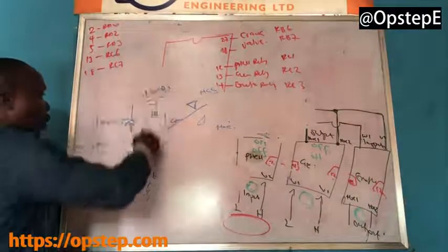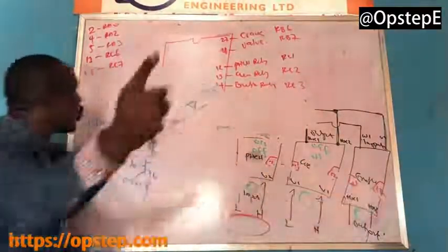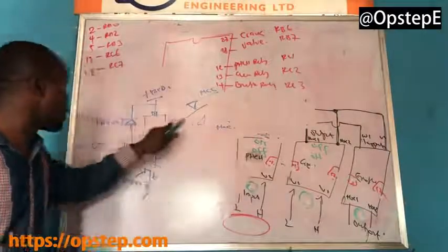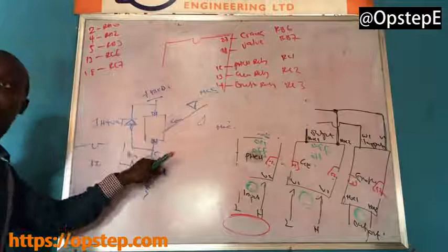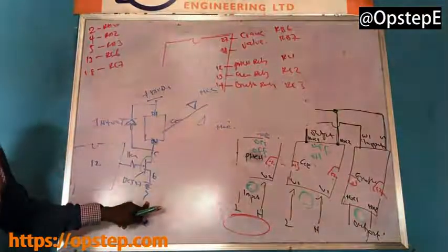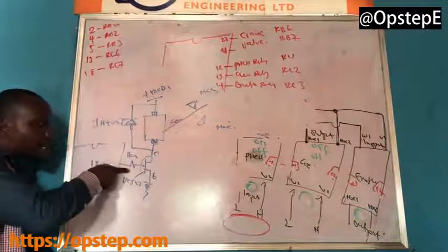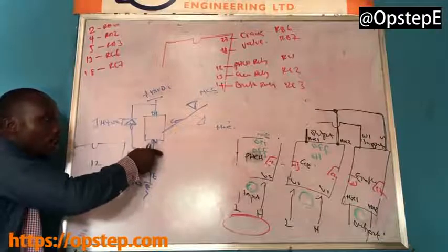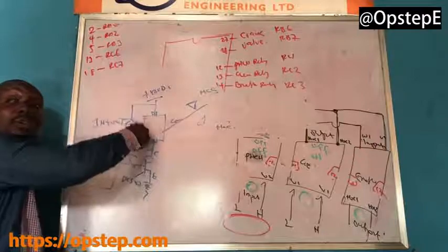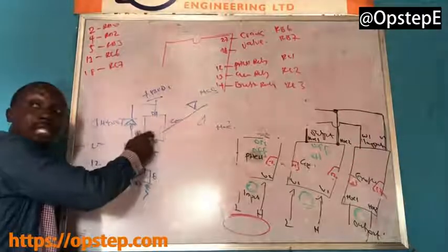So the way you see this coil connected is the way you have this coil. One part of the coil already has what? Positive of supply. The other side of the coil is connected to the collector of the transistor and through the emitter to ground. Do you get it? The question you're asking, which I've explained before, I'm repeating to you. When the base of this transistor is biased, the collector of the transistor, which is carrying the negative tag of the coil, switches to its emitter, which already has the negative that this relay is looking for. What happens?